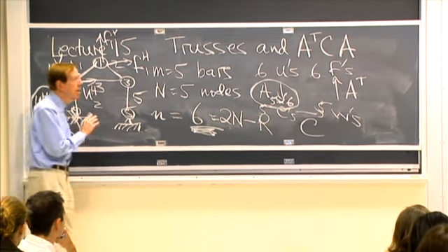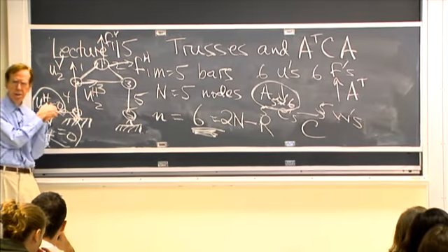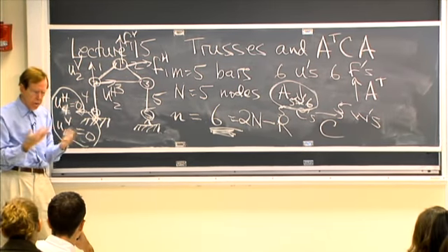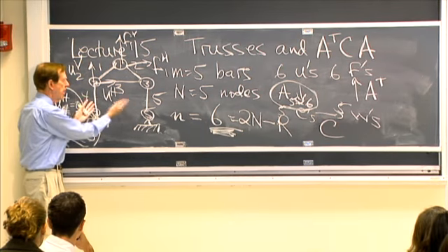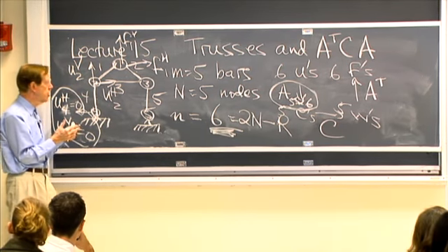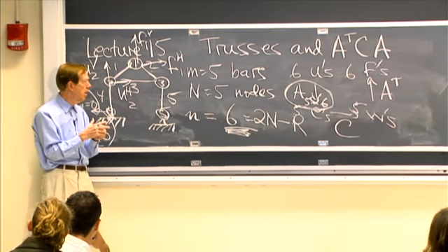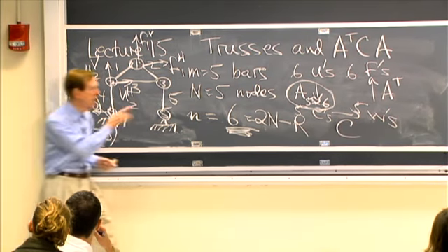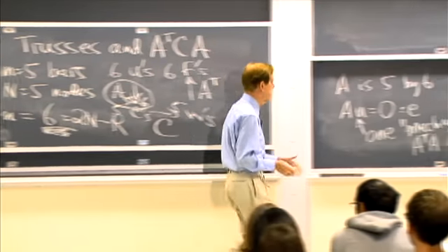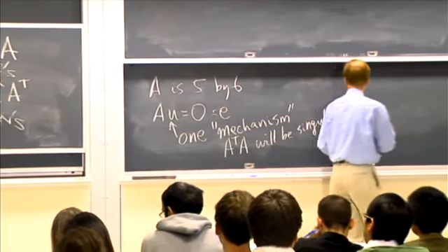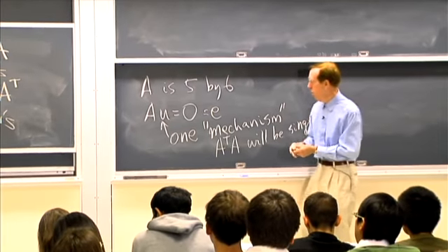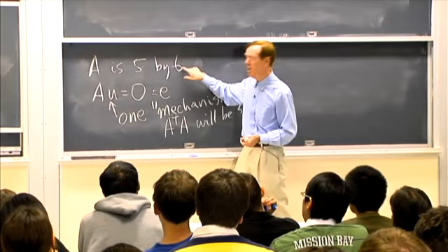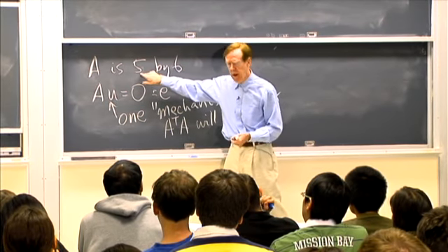And I believe that if you look at this truss, you could tell me, and you could draw a movement of that truss in which there is displacement, but no stretching. Let me ask you how to draw that. And I believe everybody understood why there was a solution? It was because we have 6 unknowns, and we only have 5 equations.